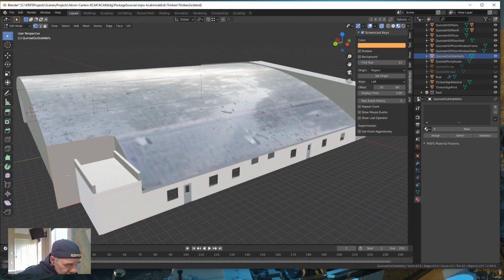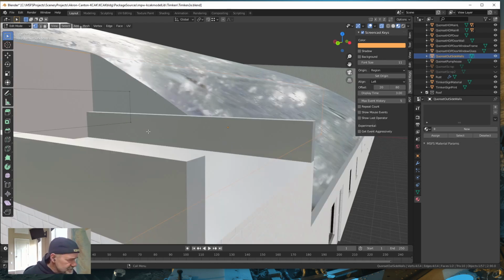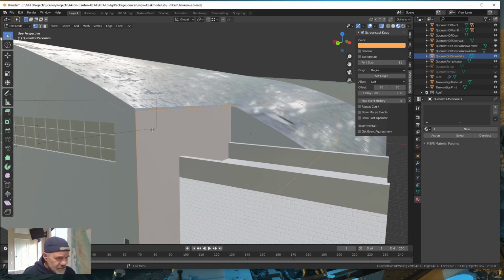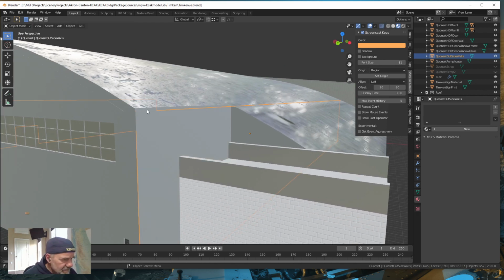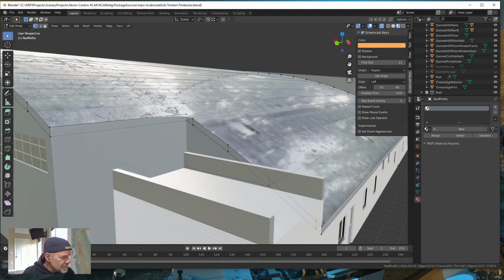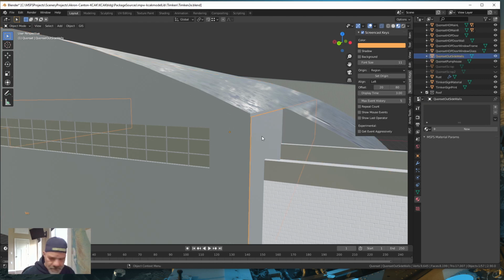we can, now that's interfering with our fascia, I think. So if I tab out of that, select our roof, okay, our fascia is this thick. Okay, so I want to bring our wall down so it's even with this bottom one, so I don't have any overlapping of polygons right here. So I'm going to hit tab, select our original wall, and let's turn on wireframe.